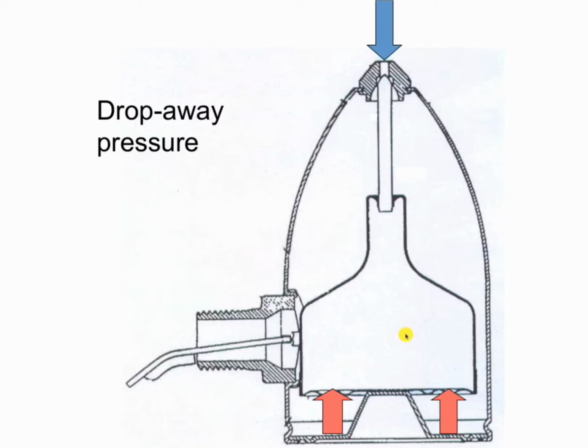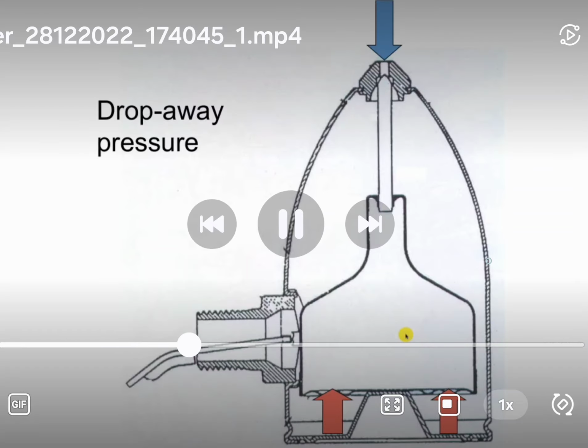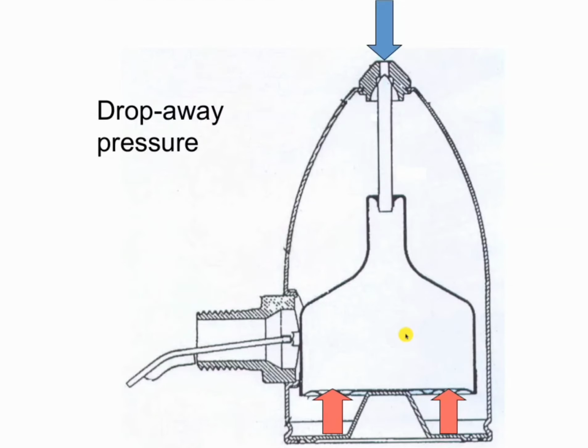And if you're running it at 2 psi, once again, like I told you, 2 psi is not going to be enough to force this vent to stay in a closed position. Not even 7.5 to 8 pounds would be enough to force this to stay up. That's just not happening. So once again, there's a lot that I really would like to know that's not being explained. Anyhow, let's continue. Steam's trying to get in, the radiator won't get hot because the air can't get out.